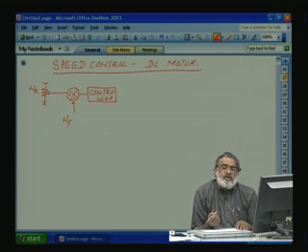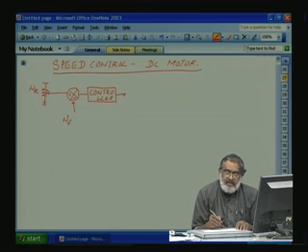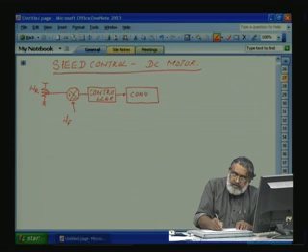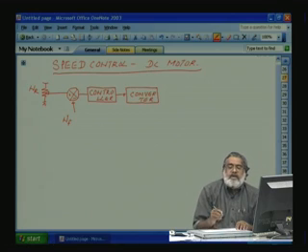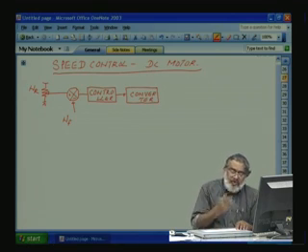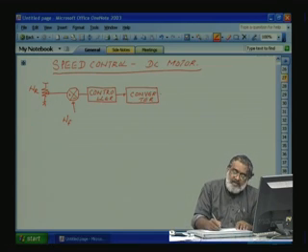Let us take a phase control converter. Then we have to control the firing angle. So this output, with the cosine comparison, is the control voltage, and it should go to the converter. I am generally saying converter. You can have a phase control converter, a front end AC to DC converter, or a 4-quadrant chopper, whatever it is. So the converter output, which is a variable DC, will go to our motor.